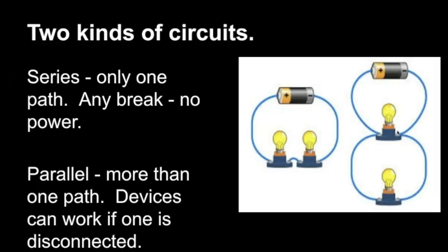Okay, this light bulb would turn off too because the bridge is out and you can't keep the electrons moving. This right here is called a parallel circuit. And here you're going to have the electrons, some electrons, they're all going to flow through here, but then some of them are going to go through this light bulb and then back to the battery, and some of them are going to bounce around and come through this light bulb and then return to the battery. In this case, if I unscrew this light bulb, they still have a path to be able to get around back to the battery.